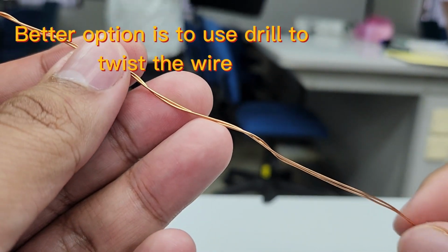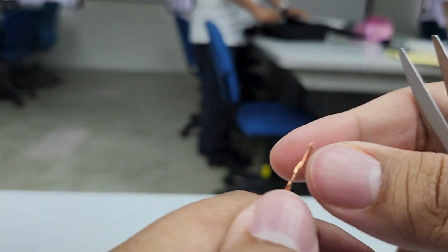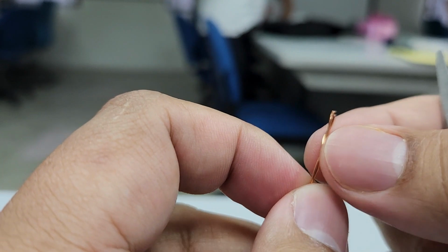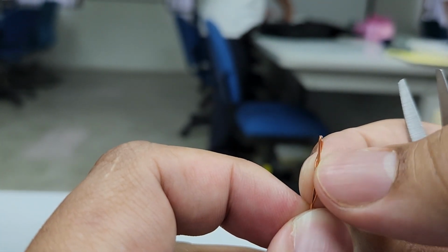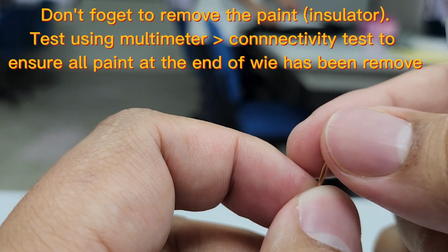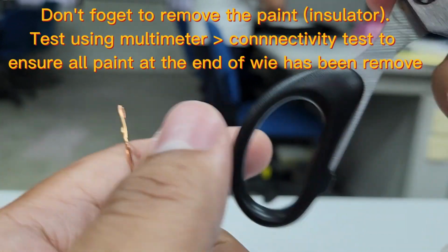I suggest you twist it very tightly. This one is not very good, but this is just an example. Then you have to take one of the ends. You have to use sandpaper to remove the pin. This is not a conductor, this is actually a pin. After you remove the pin, then you can have the conductor. This one is not conducting, it's insulated. So either you can burn it or you can use sandpaper, or I suggest you use a scissor and